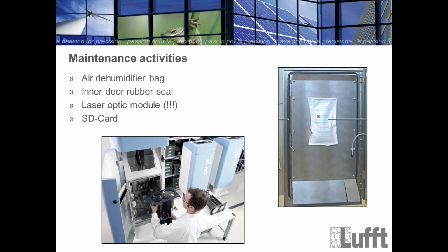And the laser optic module, which you see here in a picture, must be exchanged roughly every 3-4 years for new calibration, and maybe it can also survive for 6 years, but there's no warranty for it. So you must calculate every 4 years. You need a recalibration and alignment of these optical units. And when you do this, you wait typically until the laser diode is close to the end of its lifetime.